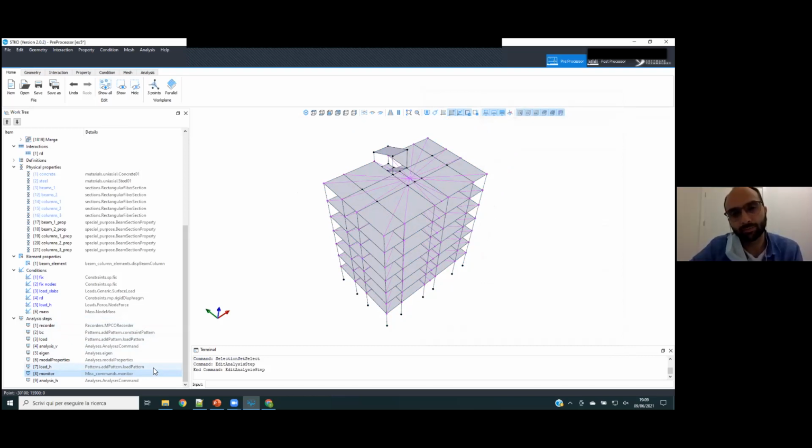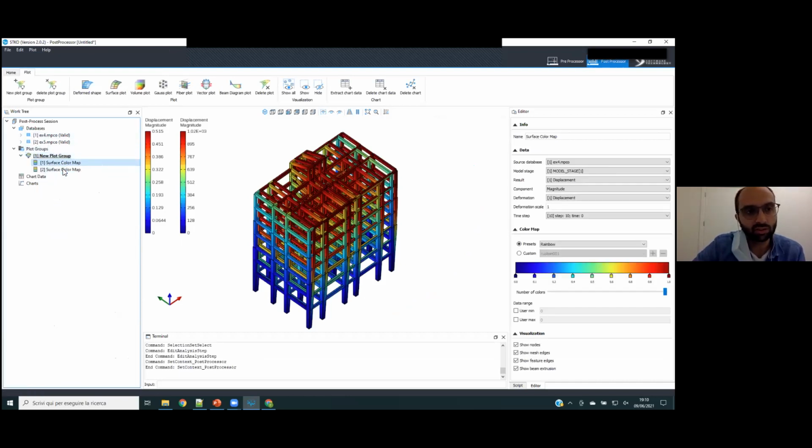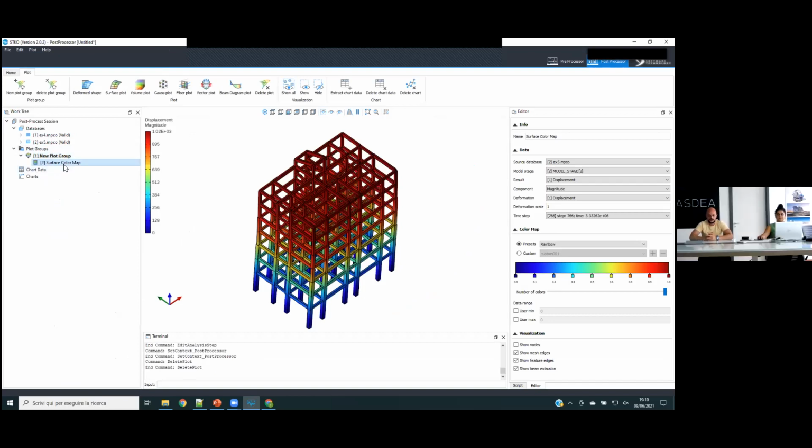When I perform a pushover analysis, does the software recalculate the nodal load redistribution based on the deformed shape, or is it inside your routine that will calculate, for example, the surface load redistributed on the beam elements for each time step, or is it inside the OpenSees software? Oh, okay, so let me see if I understood your question. The loads that you apply are just constant in space. They change in time. They are called conservative loads. If you're talking about loads that can change their direction in time, they are actually nonlinear loads, but they are not available in OpenSees because they generate nonlinearity.